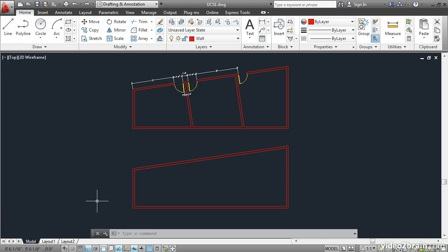You might want to change the orientation of a coordinate system to align with specific geometry that you're working on. Or you might want to rotate the coordinate system when you're doing 3D modeling. To visualize any coordinate system, you can turn on the UCS icon. Type the command UCSICON, which again stands for User Coordinate System icon, and press Enter. Turn that on, and you'll see this icon appear.